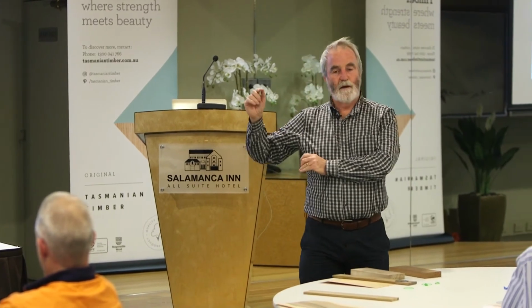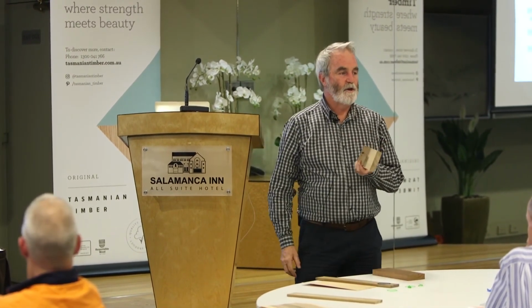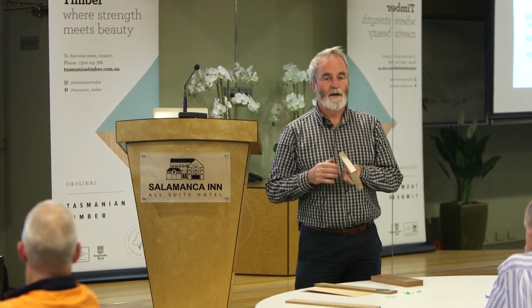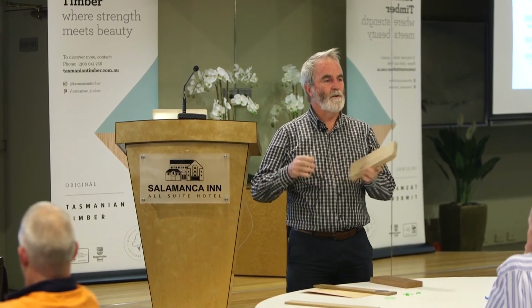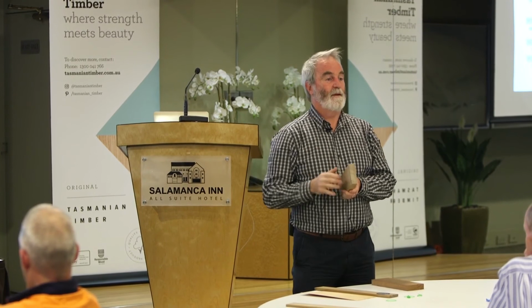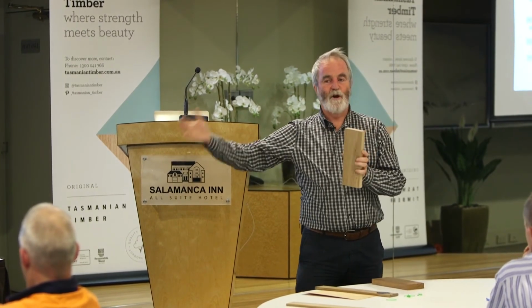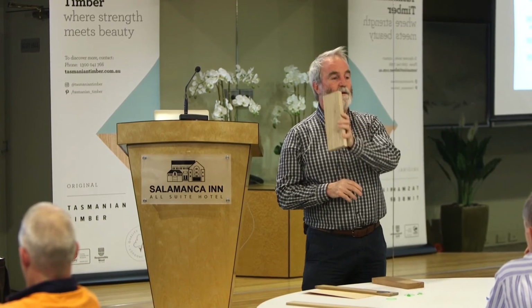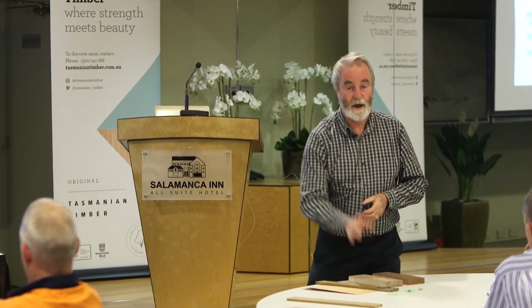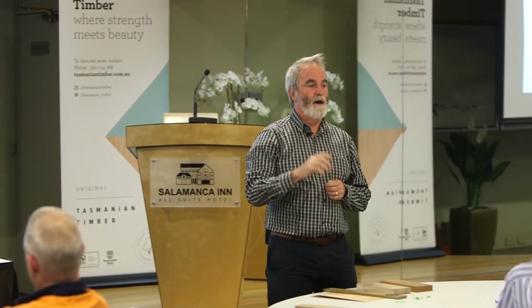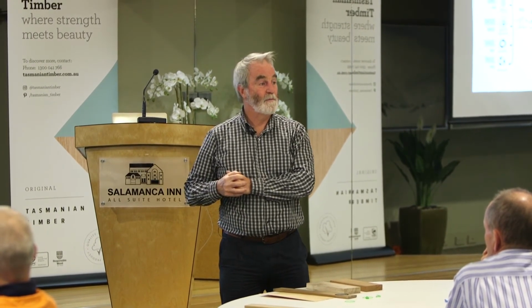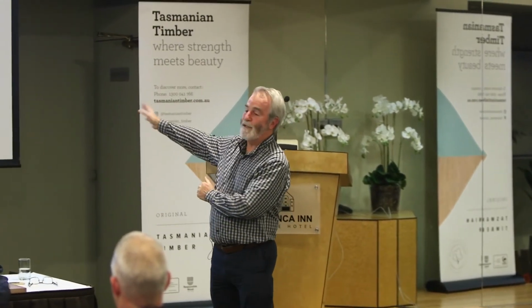The next thing is that if you're using a wood bit and you're not using a steel bit, on average, you're saving as much again by not using the steel. Does that make sense? So if you had to use an element, you save about as much from not using the steel as you sequester by using the wood. So for every cubic metre of hardwood we use in a building, you're putting about 1.6 tonnes of CO2 equivalent better off than if you'd put a steel bit in.